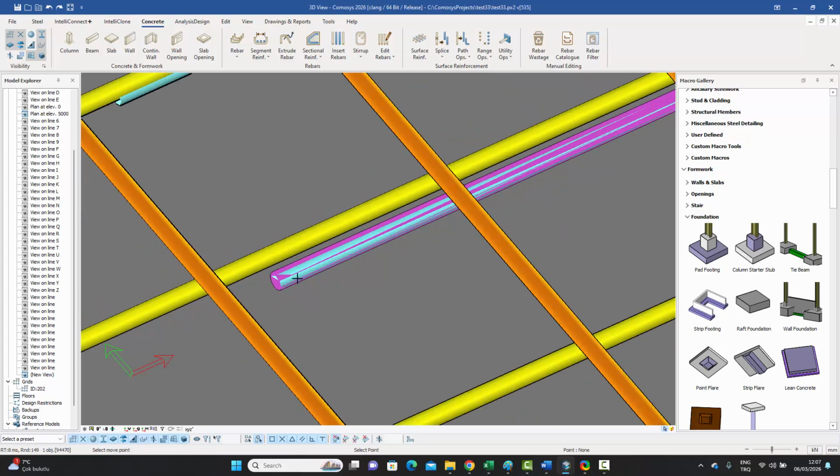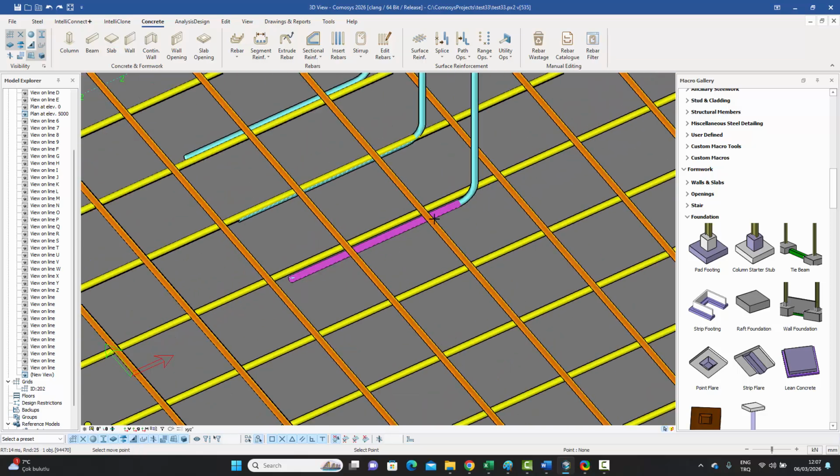When you do, it's going to select only that segment, if you notice, not the rest of the rebar. And then it asks for a point, and I can just press my control key and click on any point on this orange rebar. Just remember that when you're snapping to a rebar, you're always snapping to the midpoint. So I show it that point, and immediately this segment is offset to that point with a further offset of 5, because that's what's needed to actually sit on it.